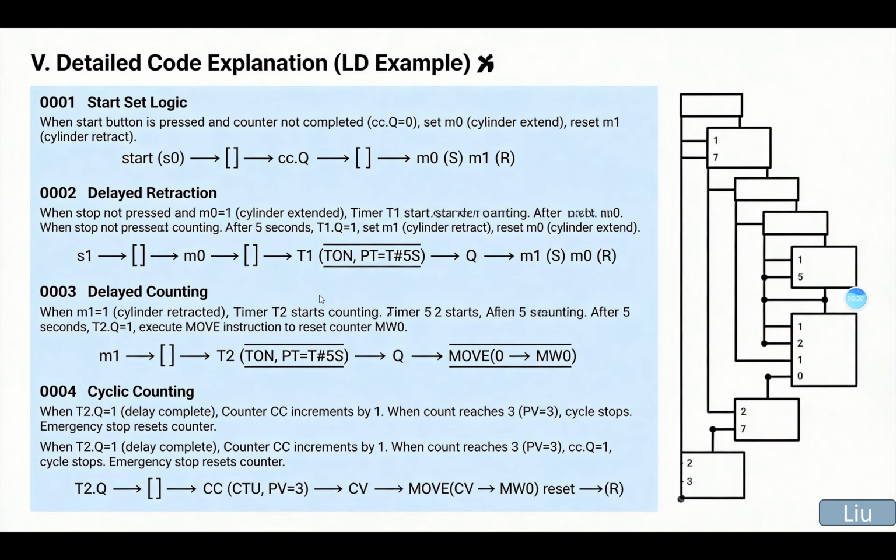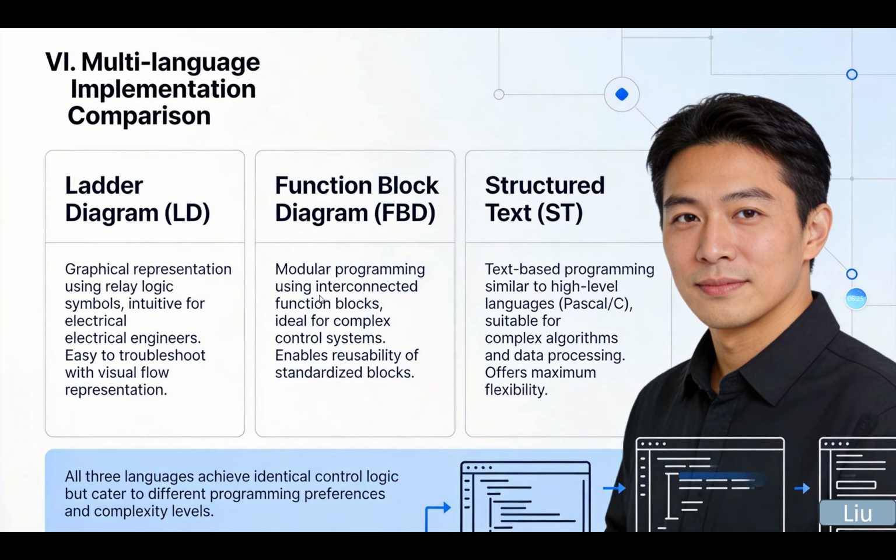So the multi-language implementation comprehension. Firstly we see the LD, ladder diagram, representation using relay logic symbols and intuitive for electrical engineers. Easy to troubleshoot with visual flow interpretation.